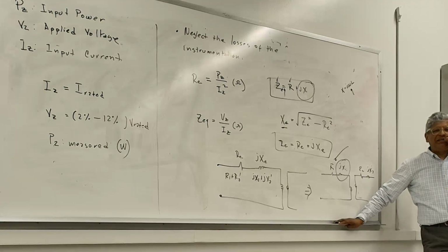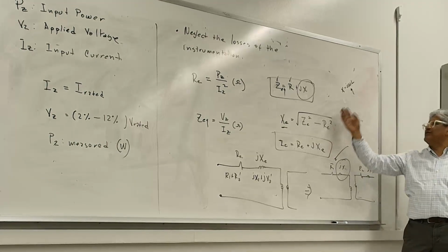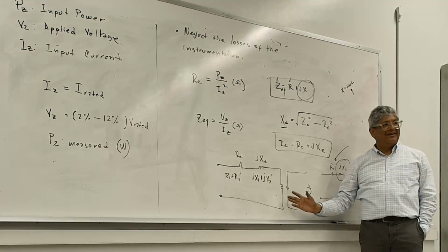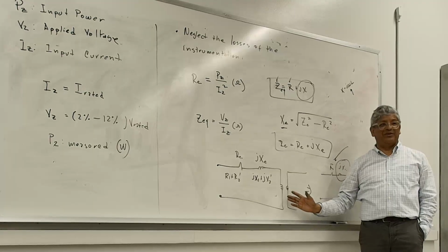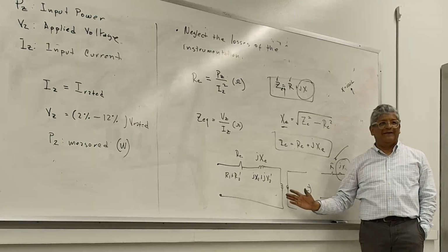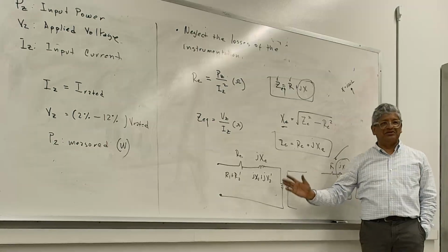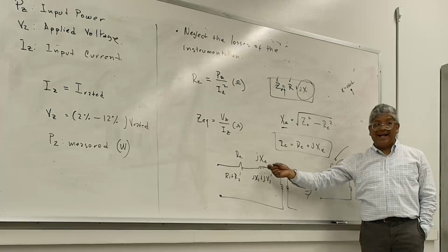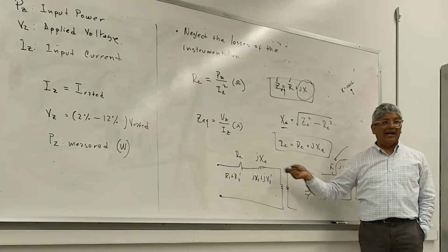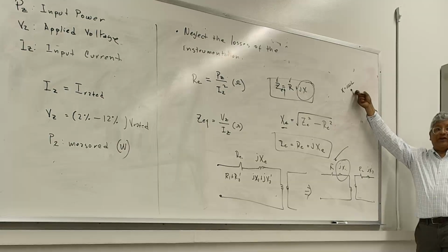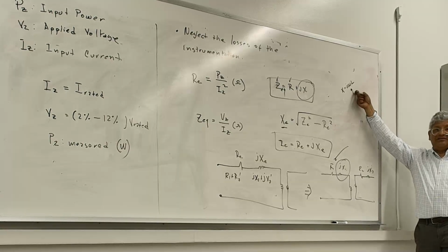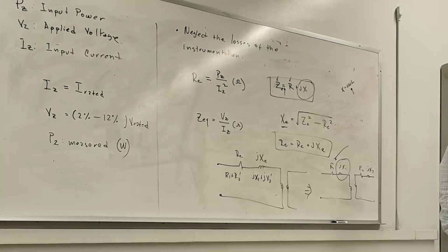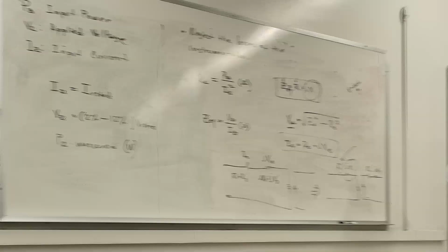Now, do you see how the transformer behaves when it's dealing with harmonics? It's not the same as when the transformer is dealing with a perfect source, or load I'm sorry, which is a 60 hertz passive load. Once you have active loads, you're going to have currents flowing here at different frequencies. It is going to affect your reactance. Your reactance is not necessarily fixed, but that's a bigger issue. That's more for power quality type analysis that you'll have to do.